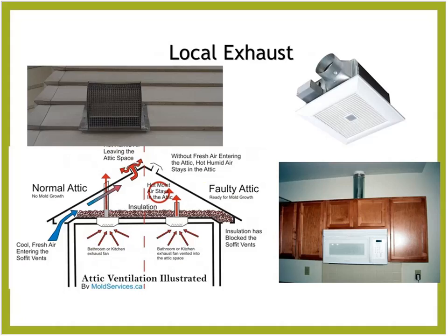Local exhaust is very important, and making sure it's done right is very important, both on new and existing homes. If you're building a new home, this is an easy one. If it's an existing one, especially existing multifamily units, it might become a little bit more complex on how to properly ventilate. But the way to properly ventilate both the kitchen range hood and the bath fan is to avoid humidity, and then of course in the kitchen there are other toxins coming off, especially gas stoves where you have open flames.